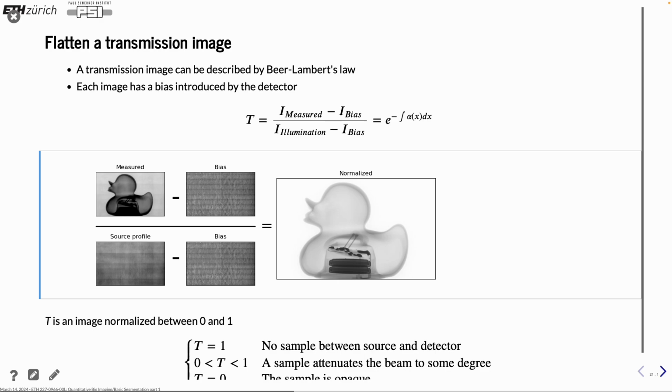That is a simplification because there can be, for example, detector lag, where the scintillator may still afterglow, and if you do it too fast after, then you would get some afterglow effect. So you always need to wait a little bit before you do this dark image. Or do it the very first thing you do.